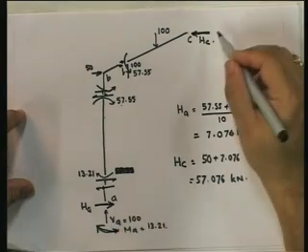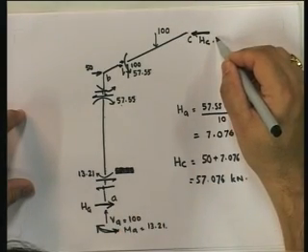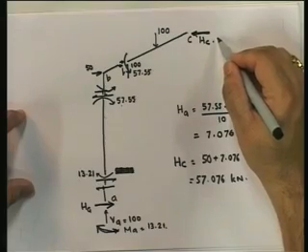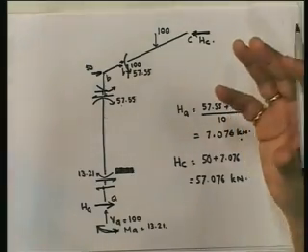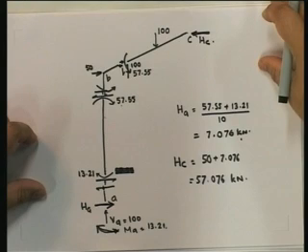Okay, in the previous case, what was this? 15. HC becomes 57.076. What was it before? 65. So we seem to be going in the same direction. Same direction meaning that the member end moments and the support reactions seem to be all less. Okay, so still we think that things are going to improve. Now since I have got this, I can actually find out the support reactions, and this is ultimately what the structure looks like.